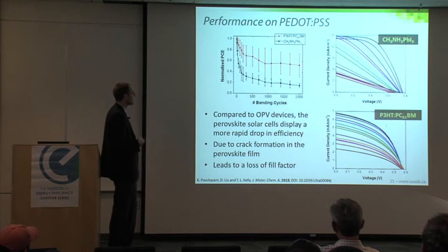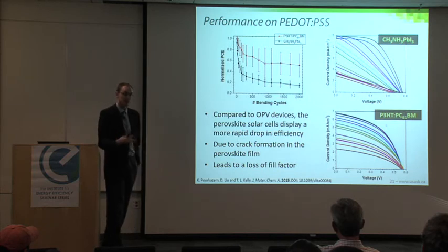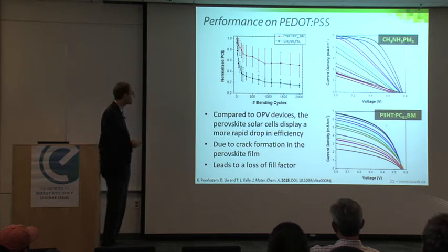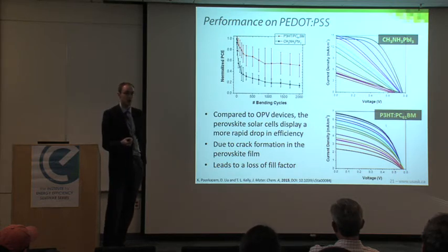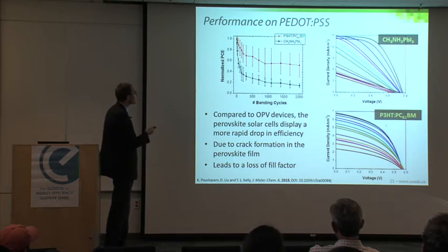So we built some devices. We mechanically fatigued the devices in the same way and compared them to organic photovoltaic analogs. So we built some P3HT:PCBM control devices, again on the same PEDOT:PSS highly conductive electrode.